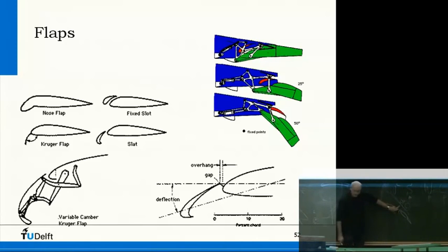Which means that the force on the boundary layer is also getting towards having it separate. So you need to take care that the flow does not separate over your flaps, because if it does, then these are not effective anymore.